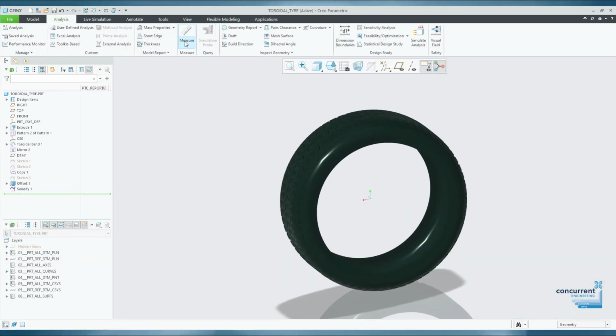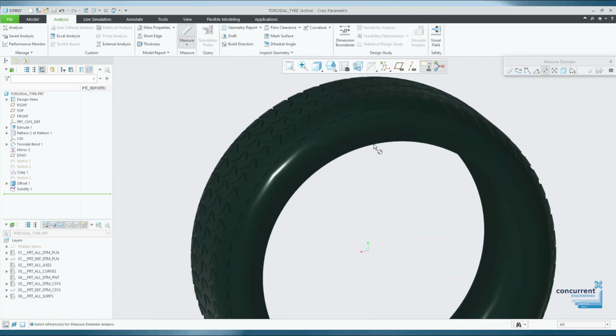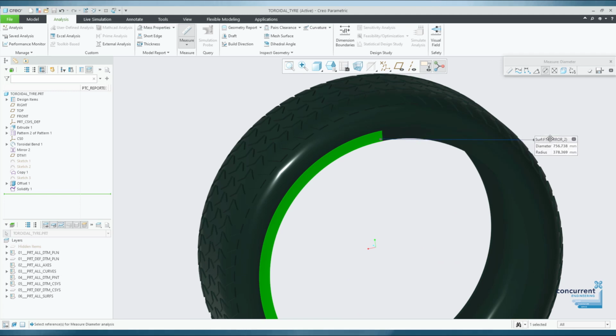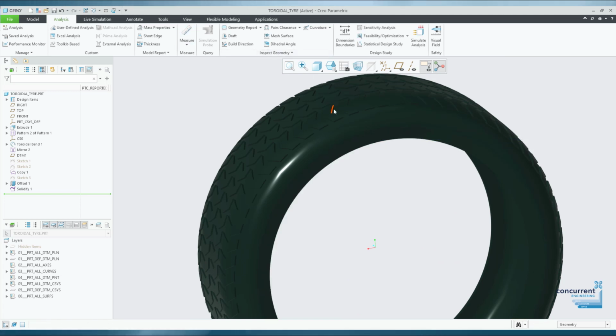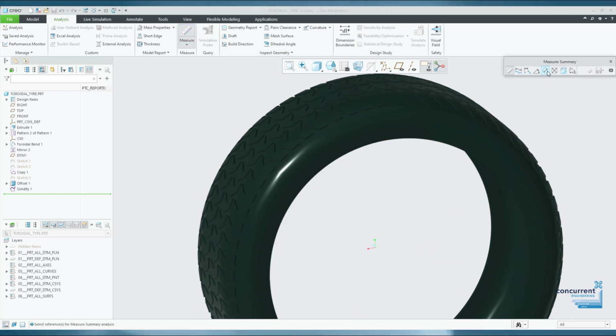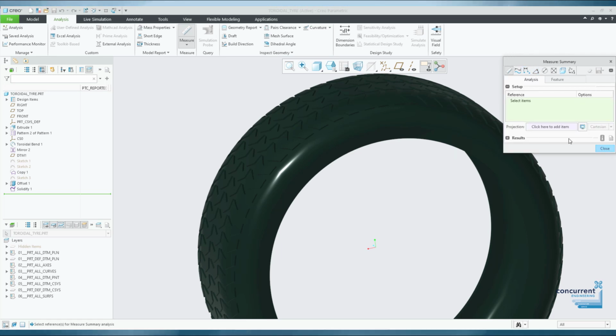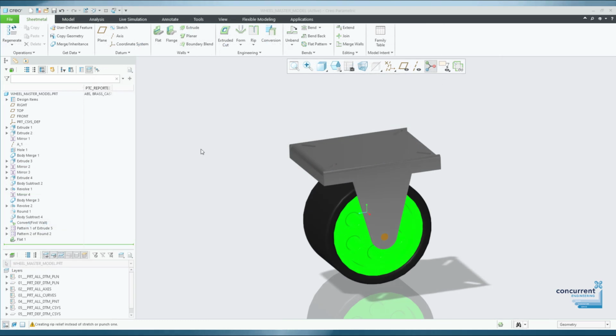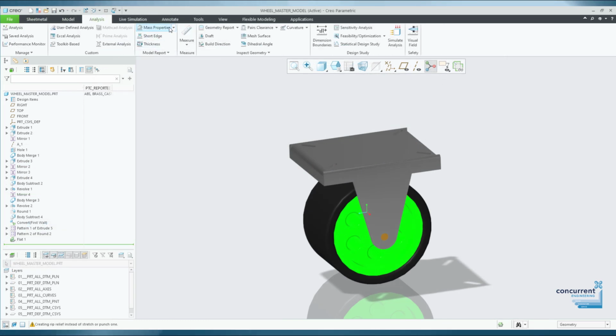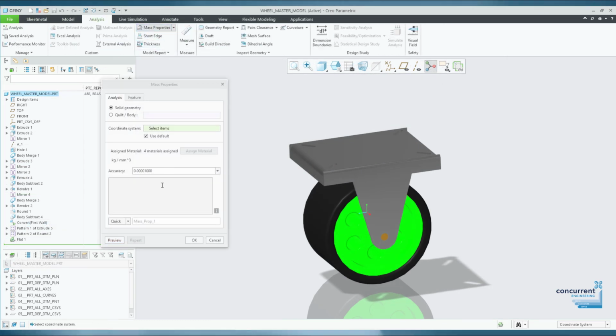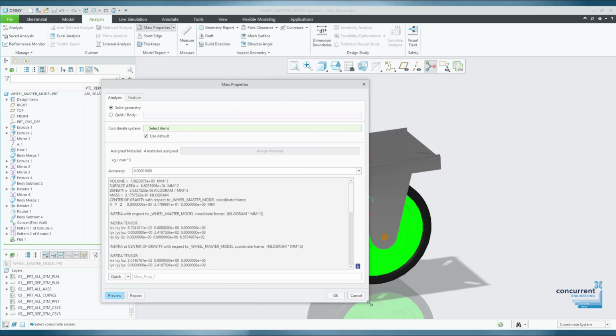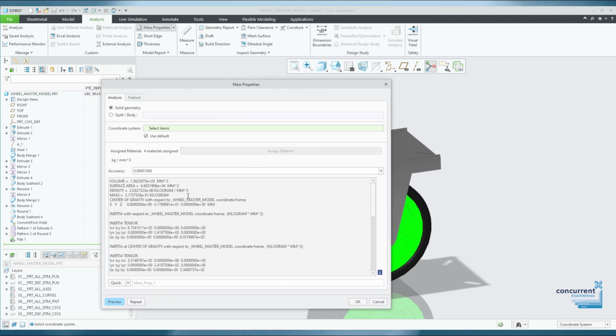Of course, every company will have its own specific requirements related to templates, and there are a multitude of options that you can control. Some companies indeed use what are called start parts for all of their designs, which will have a preset combination of requirements for every part and assembly. Now this is of course a more involved and comprehensive task, and one that is individual to each company's requirements. However, setting your part, assembly, sheet metal default unit is a straightforward task, and one that can be controlled and stored in your config file.